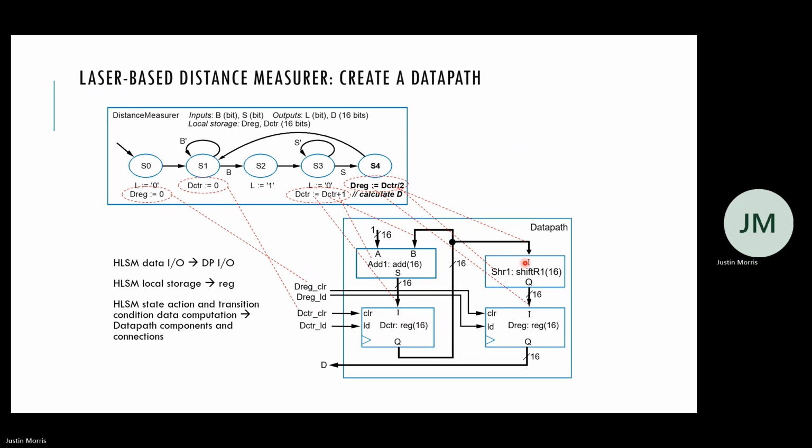Question? There's 16 bits. So there's 16 D flip-flops inside them. One for each bit. Right, it's exactly what you did in the counter lab. Okay. So the clear just makes all of the flip-flops or the bits of the register 0. The load just means that I'm going to allow this input to be saved into my flip-flops. If load is 0, then I keep my previous value.